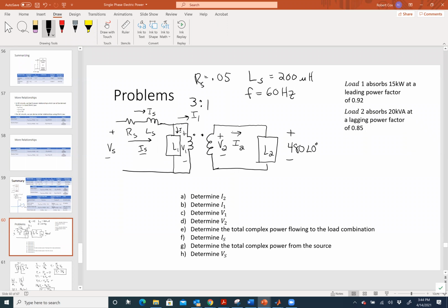So that'll get me to the complex power coming out of the source pretty easily. Once I have that I sub S, how do I figure out the complex power coming from the source? V sub S times I sub S conjugate is the power coming out of the source. So when we do the KCL, we're getting the non-conjugate. When you do KCL, you're just doing KCL for current, right? I can do KCLs for conjugates, I guess, if I wanted to. The same thing would be true. But in this case, I know I1, do KCL to find I sub S. Conjugate only comes into play when I'm talking specifically about complex power, right? So those are all my steps.